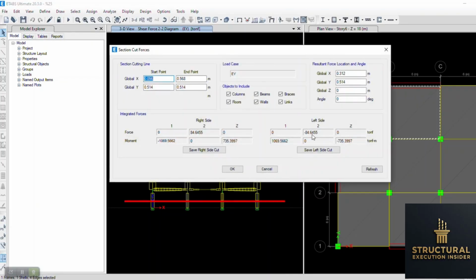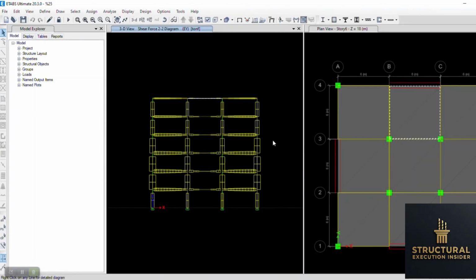If we activate shear force display and cut a section through the structure, we can clearly observe that seismic shear forces are now transferred directly into the columns and moment frames, while the walls are excluded from lateral resistance. This confirms the correctness of the staged construction workflow.